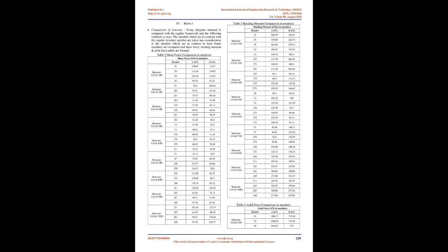3. Methodology. A 10-story RCC frame is considered in the study. In total, 10 frames are created, in which a base frame having no irregularity is compared to all other frames having different irregularities. All the seismic parameters are set according to IS 1893, Part 1, 2002, and the model is analyzed using STAAD Pro software. The base structure is symmetrical in plan and also in the vertical direction, having the same story height throughout. The structure is 15 m x 15 m in plan. Abbreviations: EL equals earthquake load, DL equals dead load, LL equals live load.